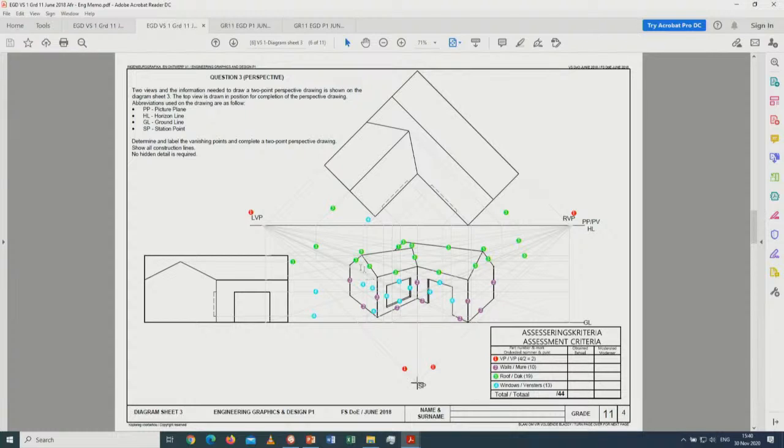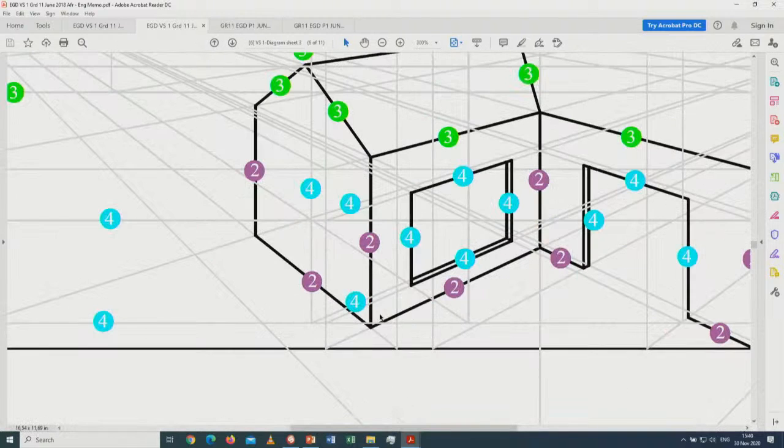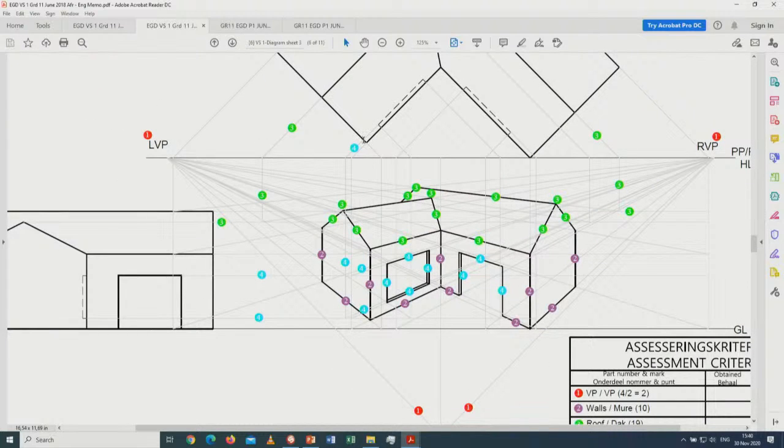So the same principle applies, where those lines need to be extended and extended to enable you to find these starting positions. Remember, we went zigzag from there, so we cut it off, and then we work from the right vanishing point to find the line from there onwards. So it's not always necessary to find that line over there before you go from there to find the point of position where it starts. You can also use the zigzag method, where you go from the vanishing point towards this position and cut it off where this goes to the standpoint, and from there downwards and cut it off over there. So there are different methods in finding those points.